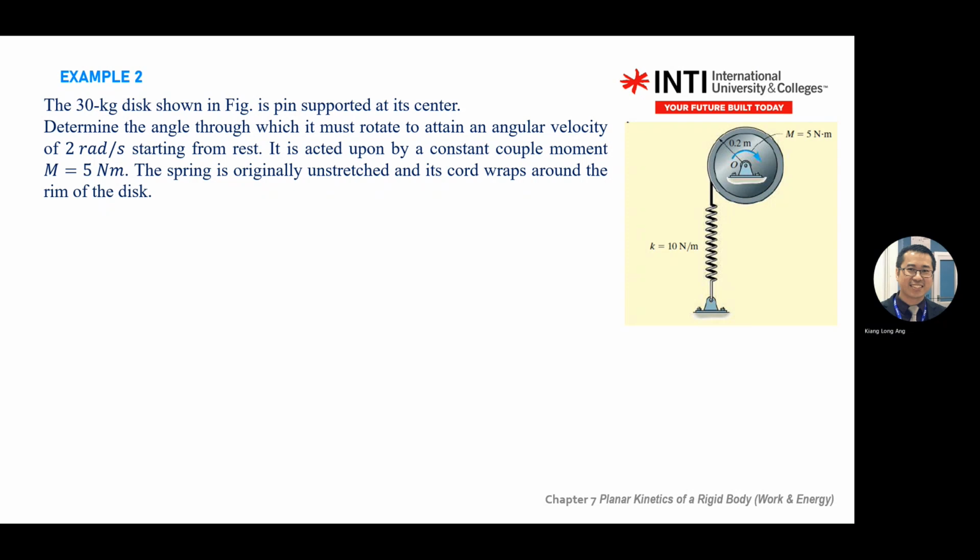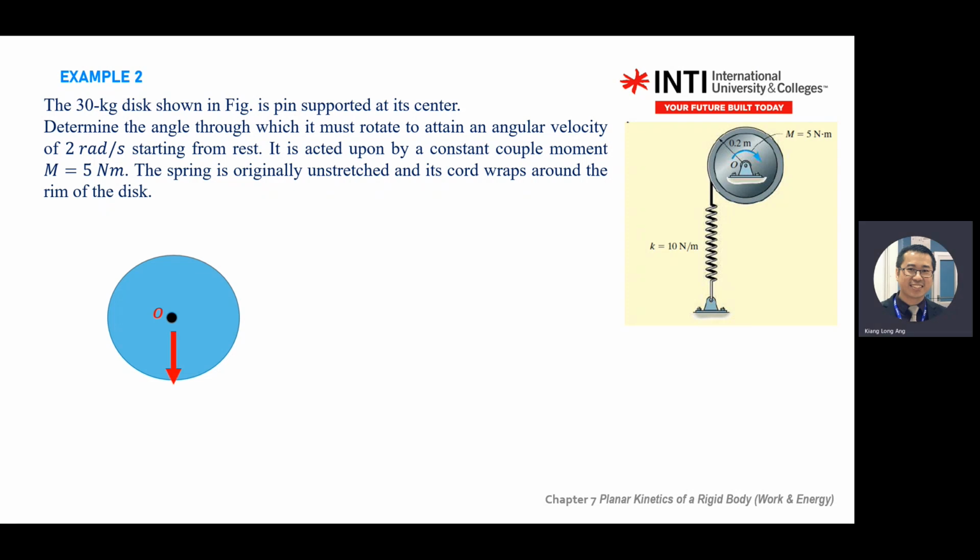So here, you calculate by using the free body diagram and the principle of work and energy. You look at the disc. You start with the center of mass. You have W. Again, when you do your test in rigid body, remember you have a weight. Because when you reach chapter 7, most of the time in test 2, I see students can do all the external forces, but in the free body diagram, they forget the weight.